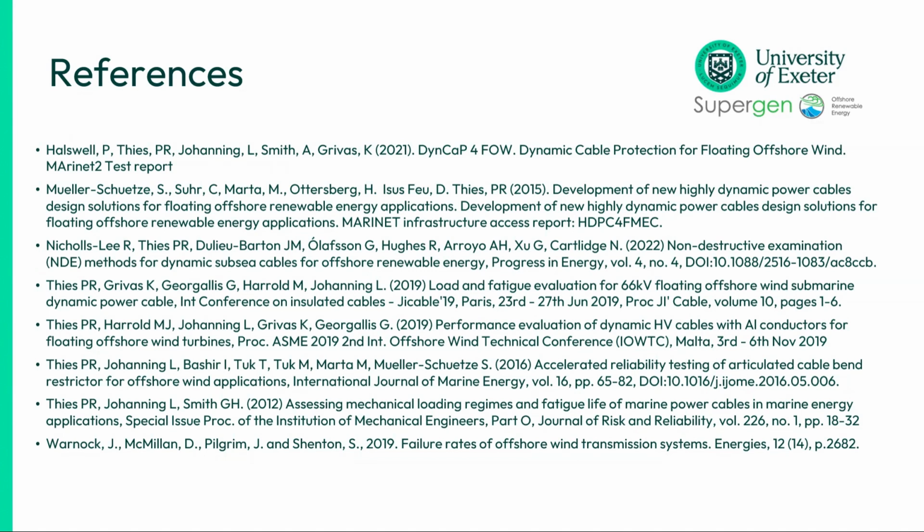And then if it is a lazy wave configuration, near those flotation buoys, and then the touchdown point. It's really those things that go wrong. And then any joints you have. So that's kind of the areas to look at.